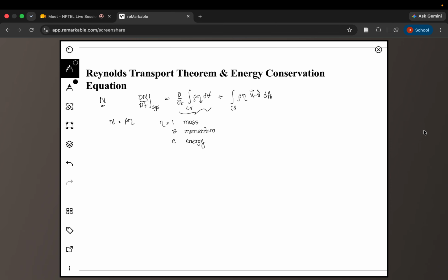So I'll just be writing the final equation, where d by dt is the material derivative with respect to temperature. So rho Cp dT by dt is the total energy, which can be written as rho Cp times the total material derivative. I have taken rho Cp outside. As I said, this entire course is on incompressible flows, and as we discussed last week, we are assuming density to be constant.